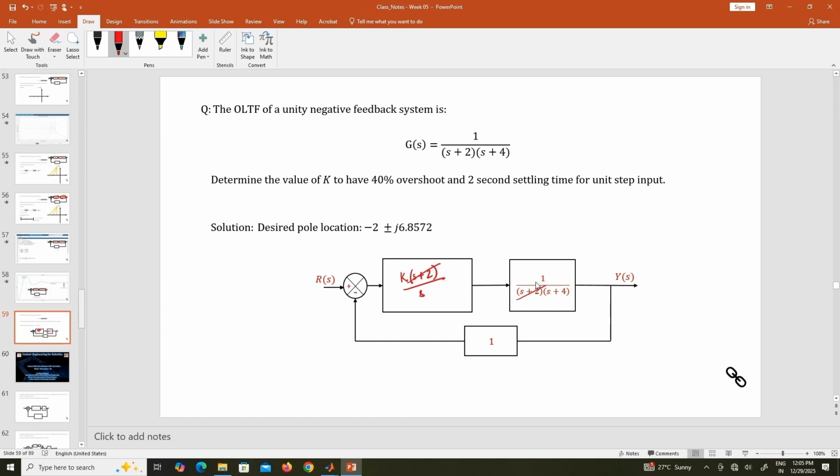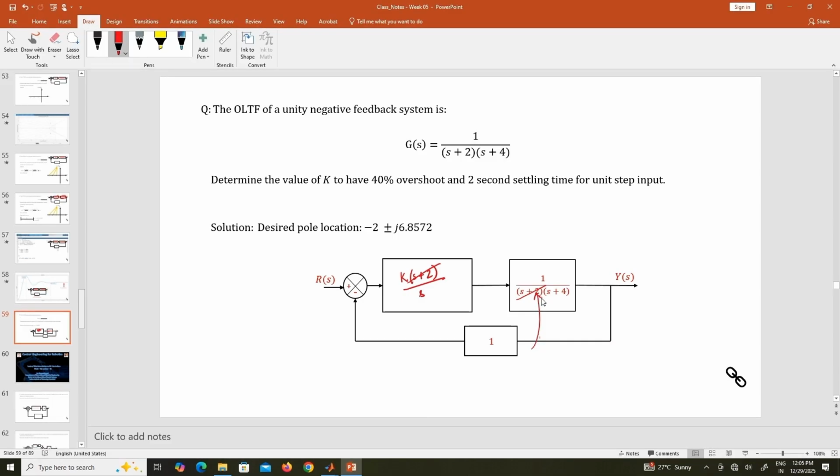This will show up with some other problems when we look at it from a modern controls perspective of state space and all. So we try to avoid this. First problem is that, and second is, you might not even know where your open loop pole position is. In that case also, to get to this exact 0 will become a problem where you are cancelling it out. Basically, you are completely changing the open loop transfer function itself, right? You are replacing the open loop transfer function by 1 by s into s plus 4. So we try to avoid these type of cancellations, because this leads to some other issues also, which we will discuss, what happens when pole 0 cancellations happen.